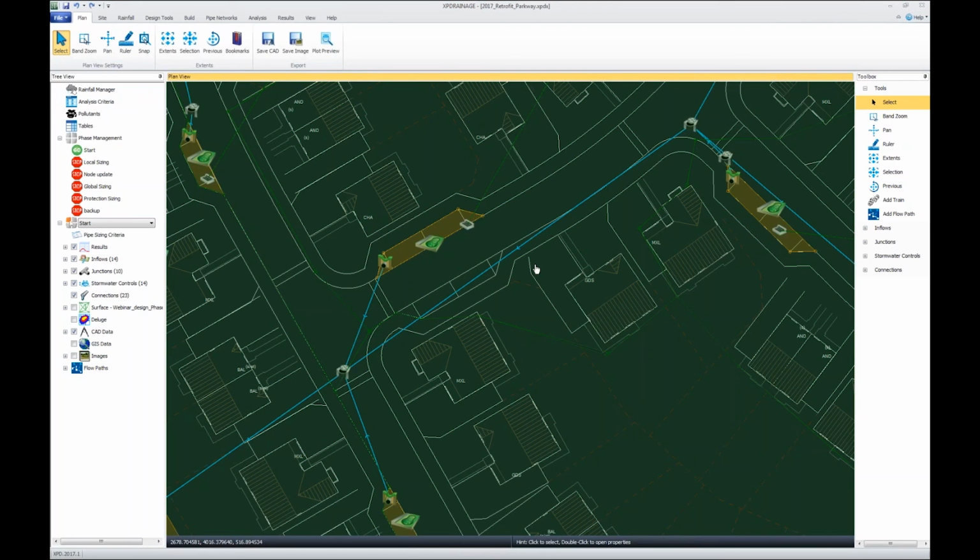That's kind of a free open source format, something that is very directly used by Civil 3D. So we're going to move our pipes and our manholes back and forth with LandXML. But as we'll find, that's not really good enough. And really that's been our focus. That perhaps is the extent to which a lot of software can integrate, and that's really as far as you can easily go with Civil 3D. So we'll start right there and look at the different ways we took this further.